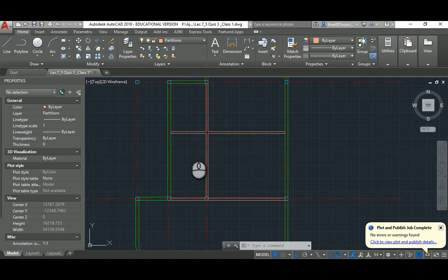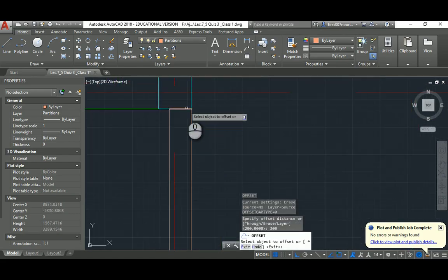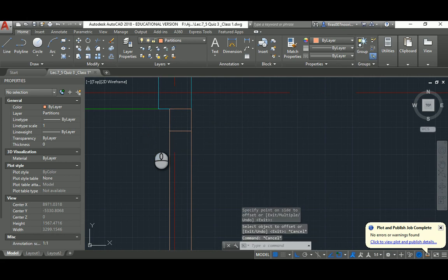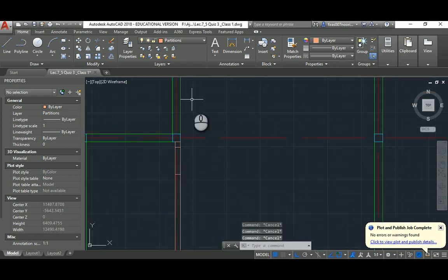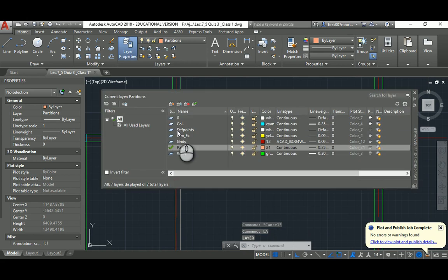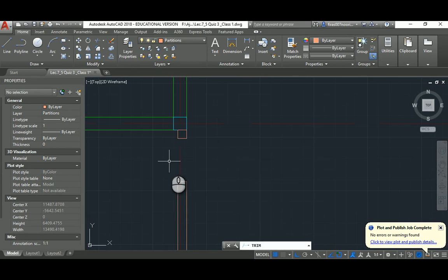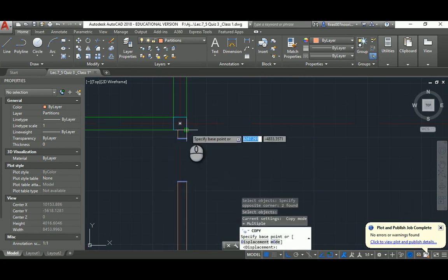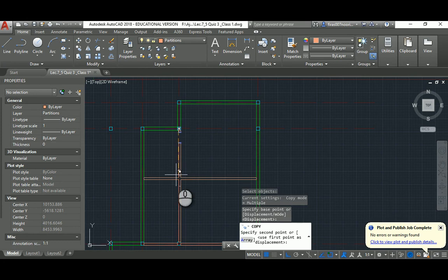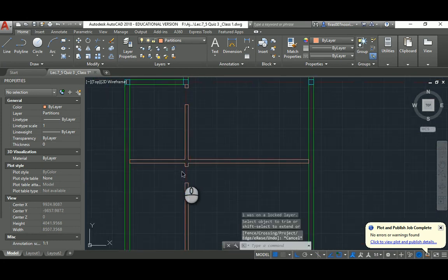That being said, now we have to do the architectural openings, and they are 200 mil and then 1000. So let's start with the doors, and it's offset at 200 from that guy here, and then offset at 1000. Probably it's the time to lock the grid so it won't annoy us. So when you trim like that, you do it like a boss here. No one can actually find a mistake, or by mistake trim the axis. Not anymore. Same here.